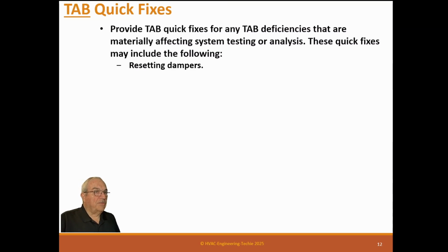TAB quick fix, resetting dampers, unblocking grills and registers. We can't have them blocked. Obviously, if you find cardboard taped over a grill, the people are too cold in the space or too warm in the space.